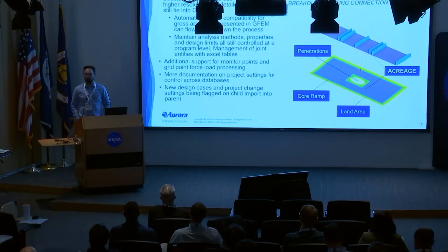And then just because I have the mic, I have a curiosity question. For this kind of vehicle, are you seeing the critical design loads come more from the water cases, or wing and ground effect, or flight cases? Depends on the section of the vehicle. Bottom pressures are very high on this. Going in high sea states, large waves, they really slam into it. Talking to boat people, they can get to hundreds of psi in certain areas, but it depends on the vehicle and your approach, and the sea states can really flow into things. Thank you.